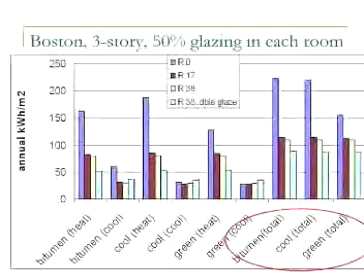And now what we've done in this case is we said, well, what happens if, in fact, I take this roof with no insulation and essentially put a cool roof on? So that's this set of bars here. So again, we have no insulation in the roof, and now I put a cool roof on. And you'll notice that, in fact, the energy use has stayed about the same. Although we still get gains in efficiency in the summertime, we're losing in the winter, because in the winter we actually want to absorb that solar energy.